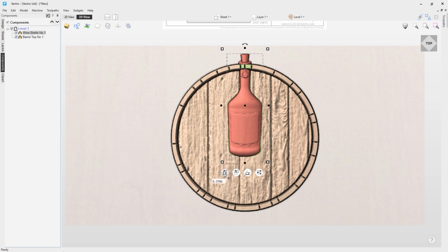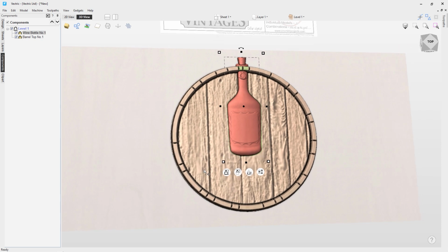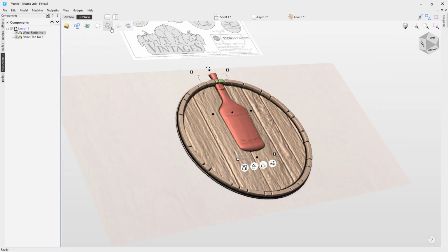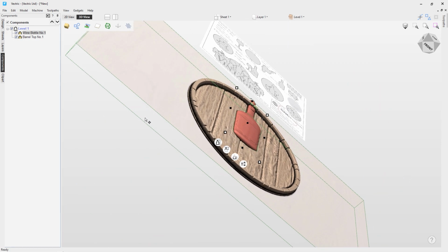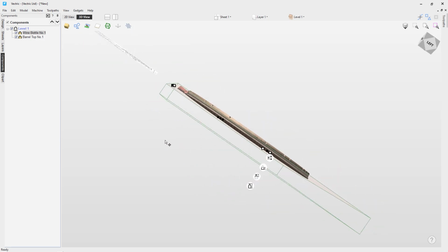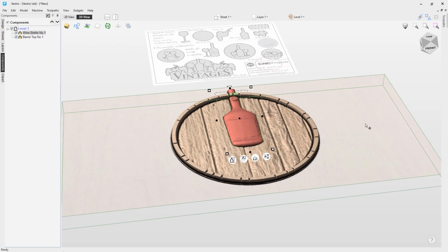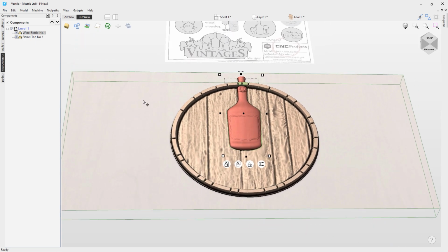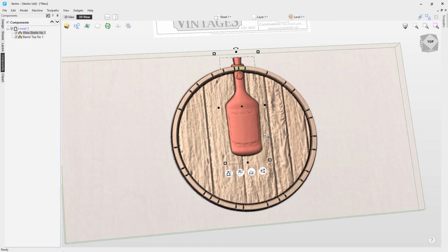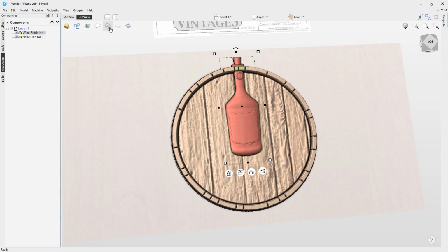Now this relates to the total height of the actual component, but I want to use the shape height, which is this option here. You can see the little triangle that represents the shape height, and you can see the base height one over here. So I can manipulate these as I need them. I can also right mouse click and I can drag my view, and I can turn on this option here to draw my material block, so I can see just how thick I'm working with, if I'm working with material where I need to watch out for how thick my model goes and if it goes through the material block.